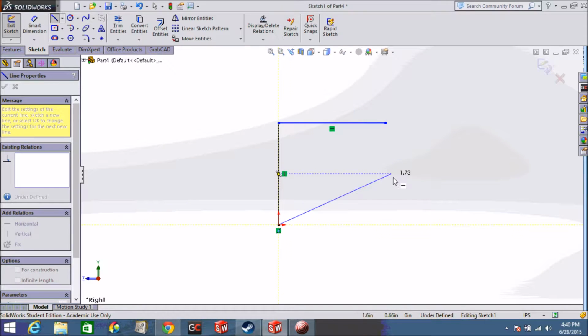So if you look, we have our third line. Now you have lots of lining up tools. If you want to go halfway up the Y dimension of the rectangle, it'll lock that in place. If you want to line up with the end of this piece, it'll lock that in place. The dotted lines pretty much explain how everything's working out here. So once again, midpoints, keep in mind that if you lock everything in place the way it needs to be, that saves you a lot of work when you're dimensioning everything later. So now I'm going to finish off this rectangle. Now we have the basic sort of rectangular shape, but there's more stuff you can do.